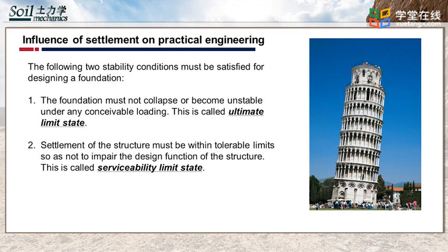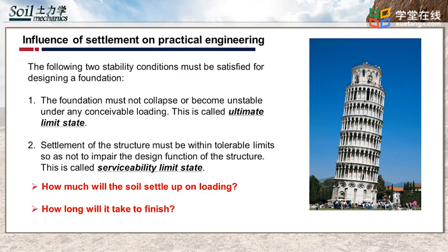It's easy to understand. Estimating the magnitudes and the rates of foundation settlement in advance is very important. Appropriate design features can be adopted to reduce settlements or avoid settlement-induced damage. To do this, it's useful to be able to estimate how much the soil will settle on loading and how long it will take to finish.